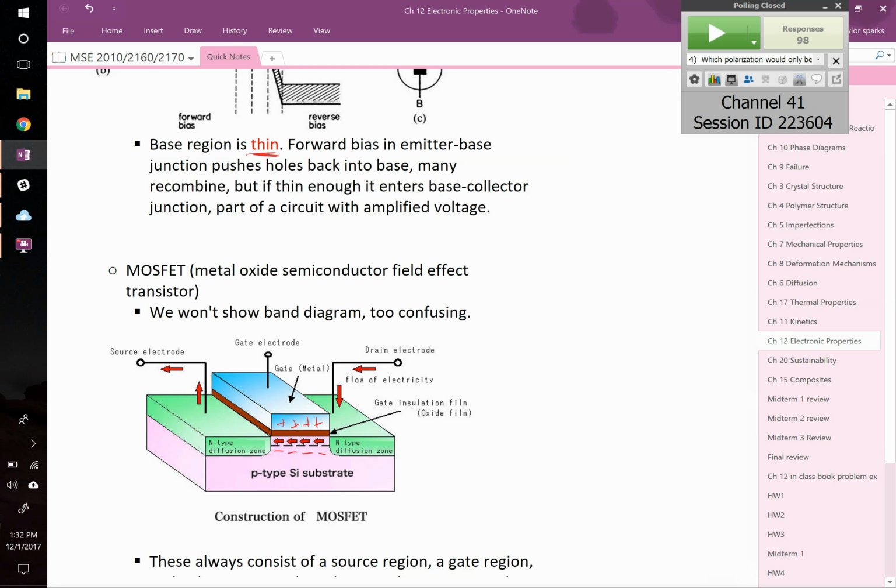So solid state memory, the beautiful thing that lets our computers start and restart so quickly compared to hard drives, is this phenomenon. They realized, hey, we can do this so small and so well, we can store memory there. If this is conducting, call that a 0. If it's not conducting, call it a 1. We can actually store memory with whether or not this gate is activated. So you have to have a way to make sure that this gate either exists or doesn't exist, and so solid state memory will decay over time. If you store your favorite electronic copy of whatever on a jump drive, eventually it will go away. Magnetic memory has a much longer lifetime, but this is much, much faster. You don't need a spinning disk head to read and write magnetic moments. This is super, super fast.